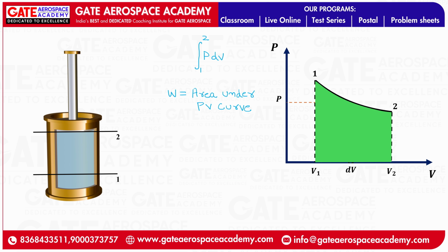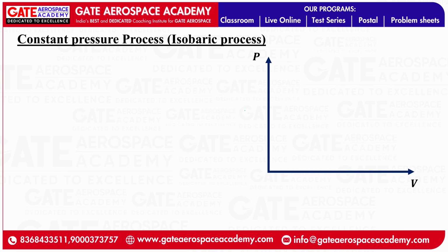Correct? Work done can also be found by finding out the area under the PV curve. Correct? So this is the important conclusion we can draw from here. We can find out the area under the PV curve, and that will be equal to work done. Right? Now coming to the process, for example, we have constant pressure process, right?